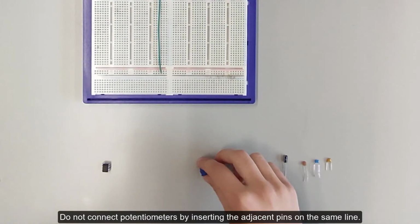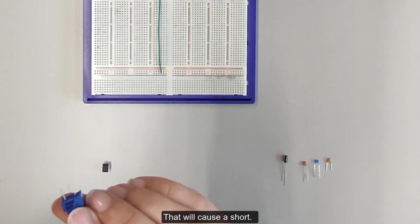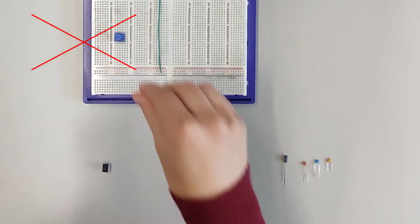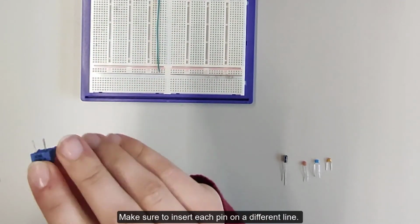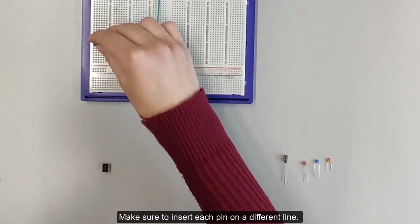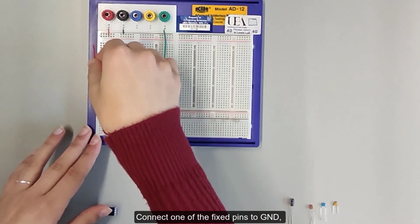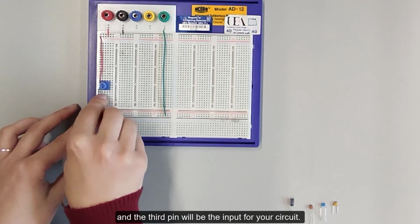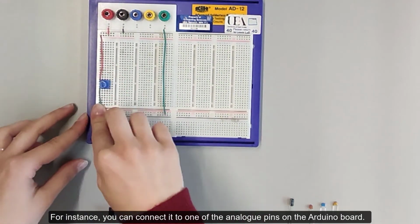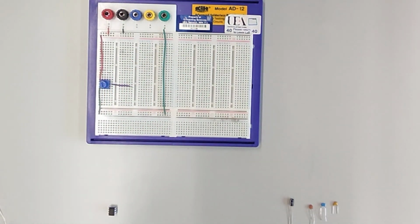Do not connect potentiometers by inserting the pins on the same line. That will cause a short. Make sure to insert each pin on a different line. Connect one of the fixed pins to ground, the other one to power, and the 3rd pin will be the input for your circuit. For instance, you can connect it to one of the analog pins on the Arduino board.